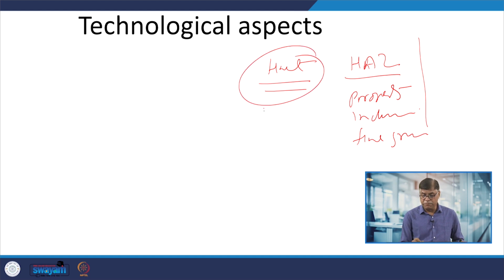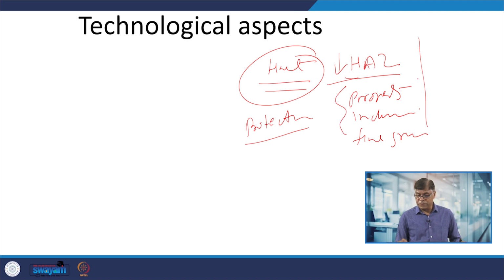So, when low heat input and proper protection to the weld pool are applied, a very narrow heat affected zone and weld metal free from porosity and inclusions are realized, and the weld metal has a fine grain structure. So, low heat input and good weld pool protection are the key for developing a sound weld joint, which will offer greater resistance to failure.